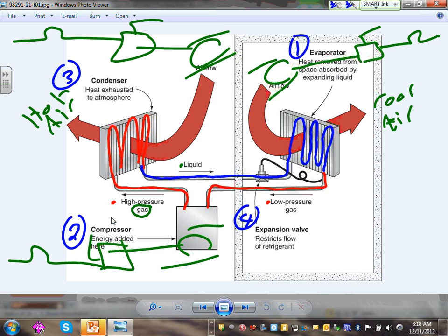If you call Dunwoody, can you imagine how you're going to cool a building like Dunwoody? They do it with a chiller. So what they do is they chill the water, the same process with a compressor and a chiller. The chiller will have a compressor in it, chill the water through a refrigerant, move the refrigerant through coils to chill the water. Then they circulate the chilled water all the way to the air handling unit.